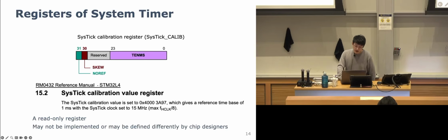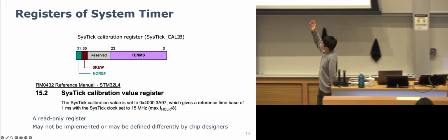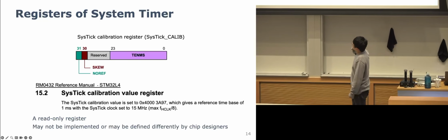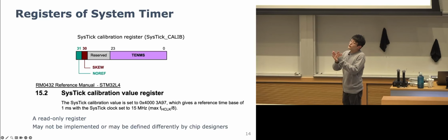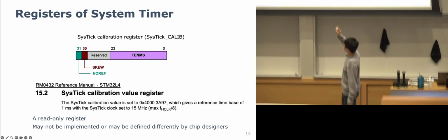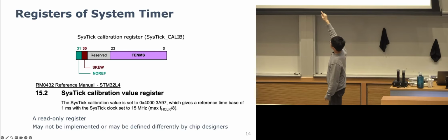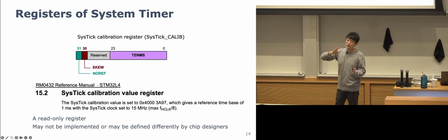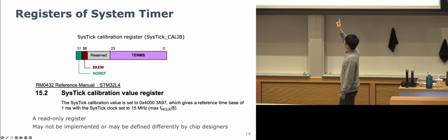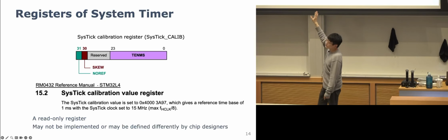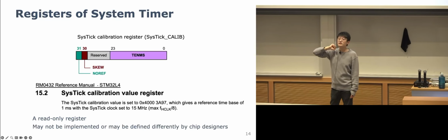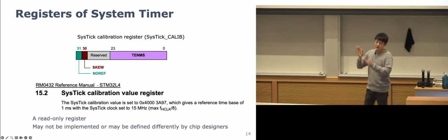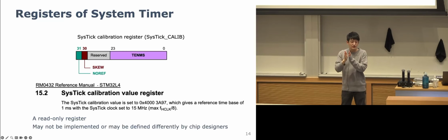So basically, what this tells you is the 10 ms number that's being used for the value you set for the interval. So essentially, if the system is currently set to this value, and you have a sys clock set to 50 megahertz, which is I believe what our board, the STM32, is doing, then you nicely have an interval from the SysTick of 1 millisecond, I think. So that can decide what interval each of these will be set to.